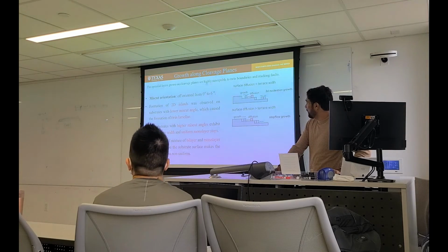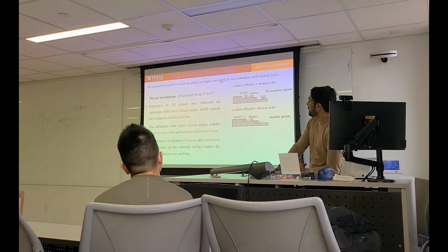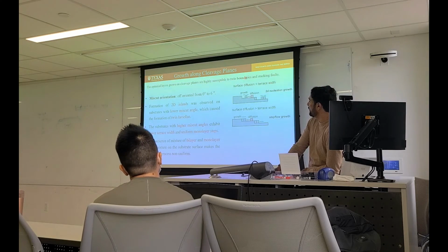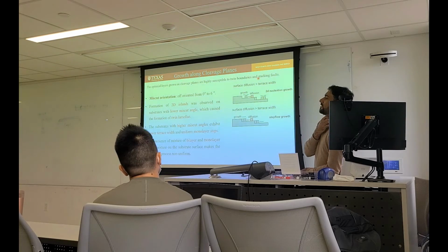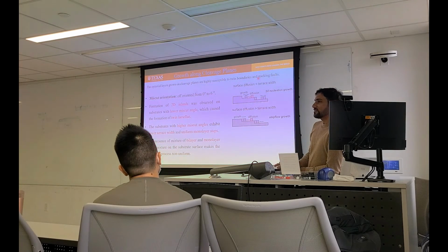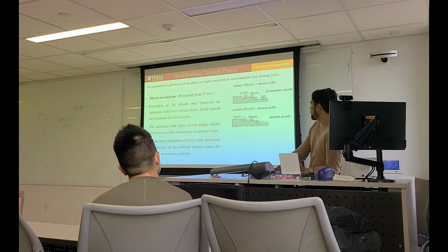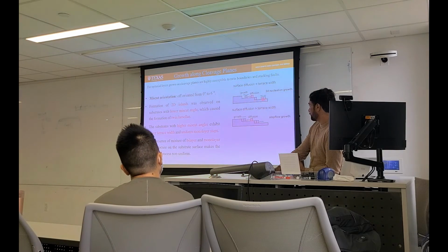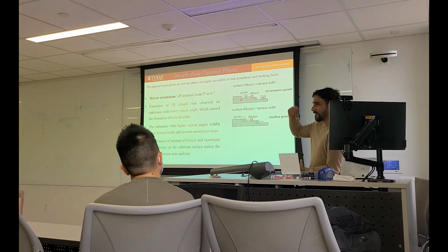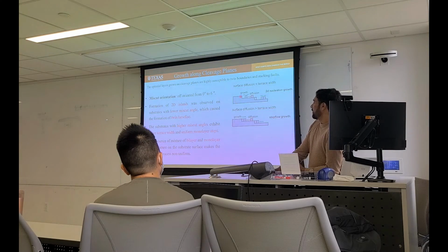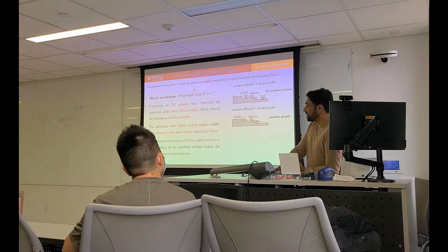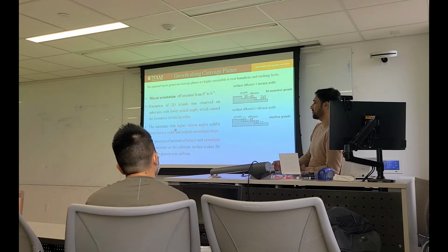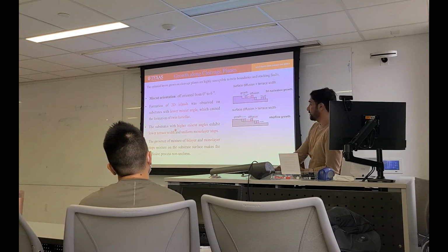Growth along the cleavage plane, the epitaxial layers grown on the cleavage plane, are highly susceptible to domain boundaries and stacking faults. The reason is that you know about terraces and kinks. Suppose this is the terrace width, and this is the step height, the edge height. There is one way to grow good crystal on the cleavage planes. Only this is the way. If you don't follow this way, you cannot grow very nice film on gallium oxide.